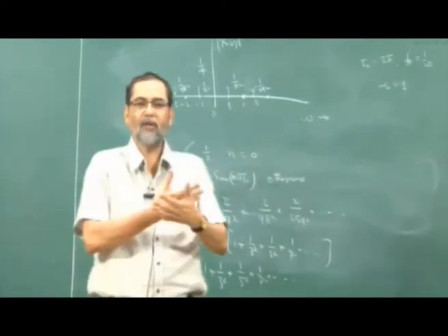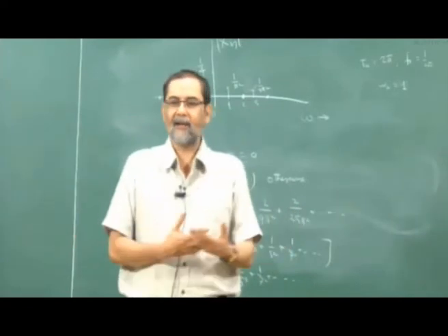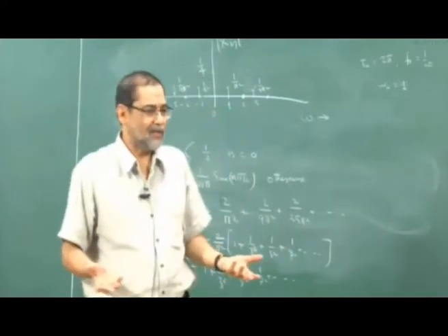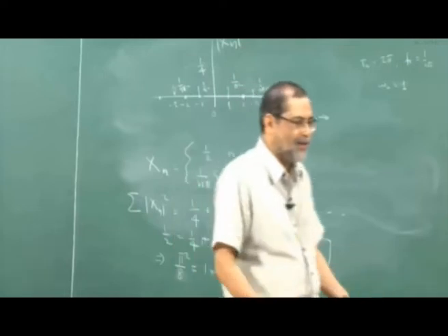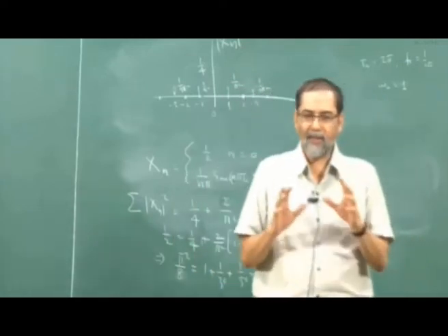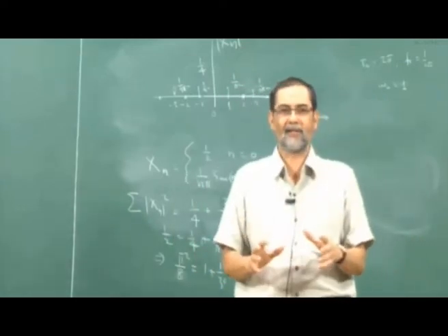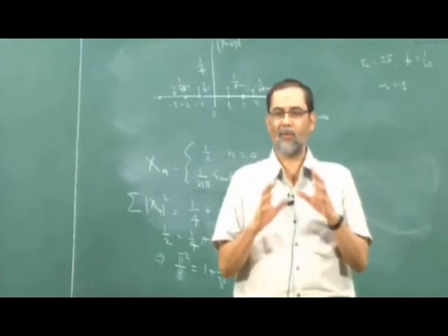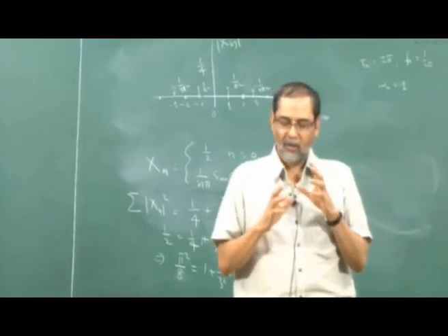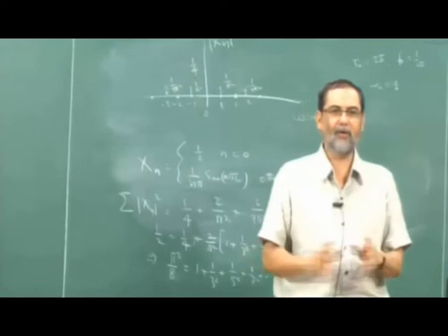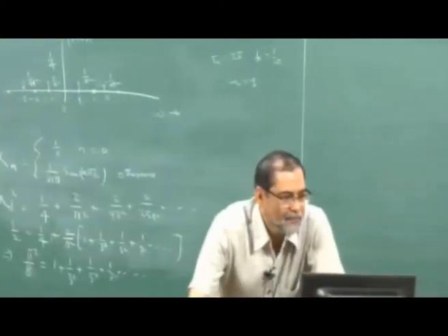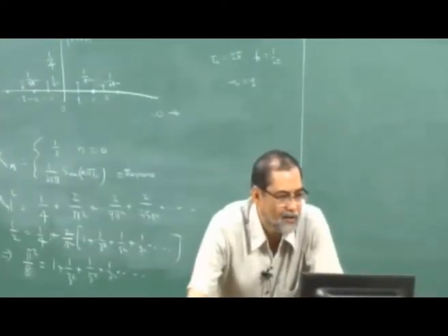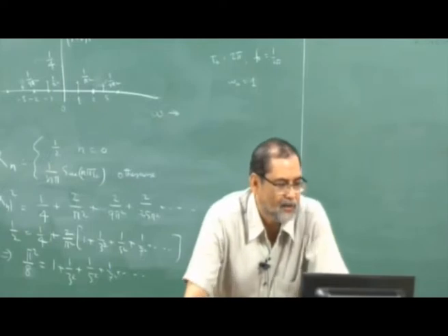So if you take two infinitely long pulses and convolve, it may not converge, and so the convolution is not defined. These are all what are called improper integrals. So if it is an improper integral, then you have to take a lot of care before you can answer that question. Give a simple example of an analog periodic signal which is not absolutely integrable.